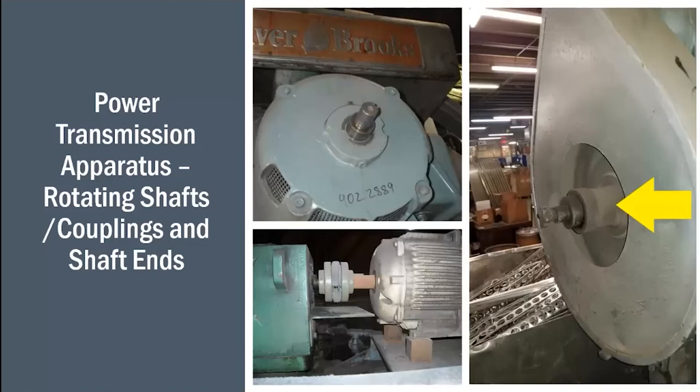Fixed guards are often used for power transmission equipment because, again, they don't need to be removed that often, but some of the issues we see around here are shafts and couplings on pumps that don't get guarded, or the guarding is constructed so that you can get past the guarding. Again, refer back to that table 010 or ANSI B11 and your gotcha stick.